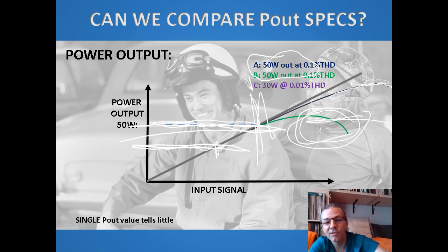And here the difference between the expected output and actual output shows up as 0.01% distortion. When you push the amp to 50 watts, it becomes 0.1%, and then it becomes bigger and bigger. So when you read that there's a wonderful amp that has extremely low distortion, it just means that they specified it at a lower power level.